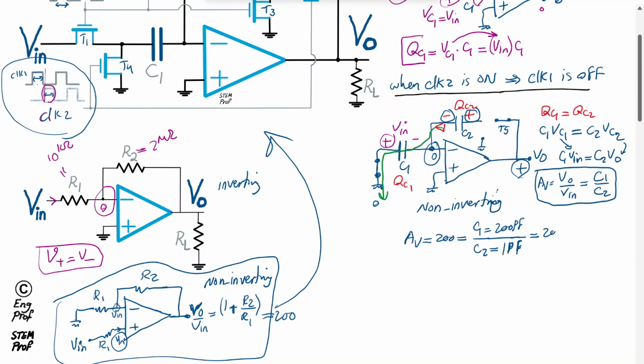So this is a gain of 200 realized, and now these are capacitors with proper sizes that can be implemented in a chip. If need be, use lower values to help with better implementation in a chip. And the nice thing is, while there are still variations for the absolute value of C2 and C1, if they are implemented, first, they take much less area compared to the realization of resistors. These small capacitors consume a much smaller area. On the other hand, if they are implemented close to each other with the same approach, then the variation of the ratio of C1 over C2 is very small.